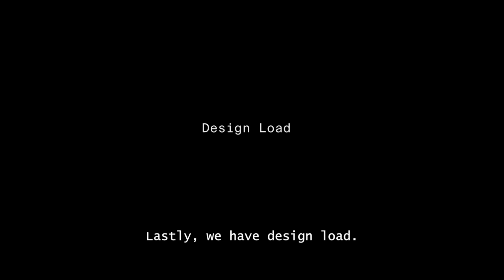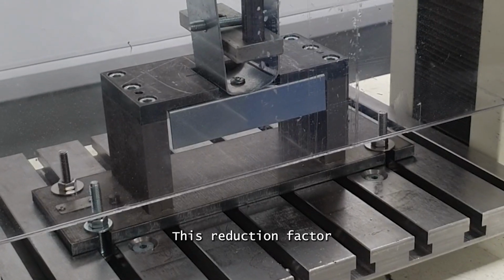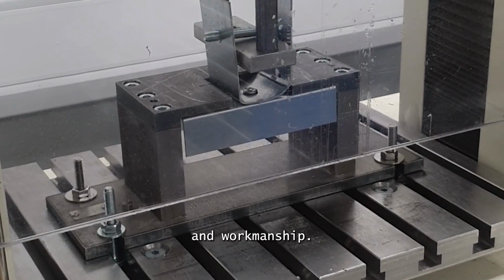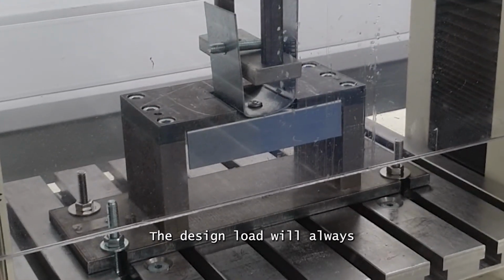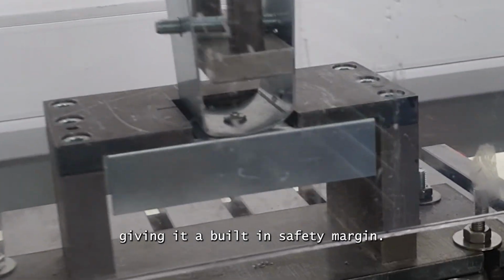Lastly, we have design load. This is calculated by multiplying the characteristic load by a predetermined reduction factor for the material the component is manufactured from. This reduction factor allows for discrepancies in the material, manufacturing process, and workmanship. The design load will always be lower than the characteristic load, giving it a built-in safety margin in case of an exceptional event.